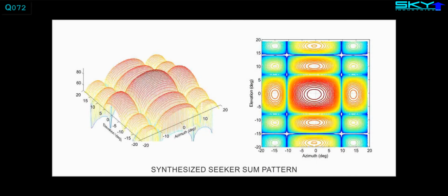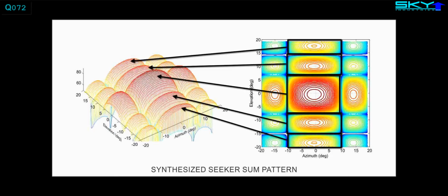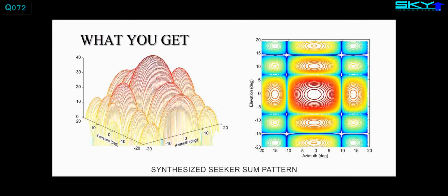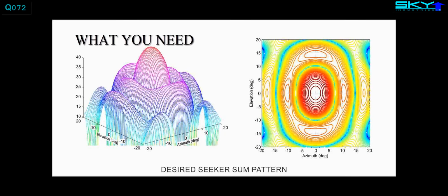Now, this innocent-appearing shortcut produces two-dimensional antenna patterns which have rectangular artifacts in them, because they're caused by the application of the azimuth cut at all elevation angles and the elevation cut at all azimuth angles. And the resulting 2D pattern does not represent the intended antenna pattern, which, generally speaking, has an approximately circular symmetry.